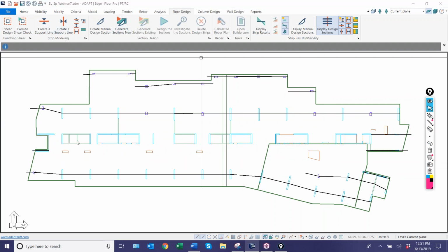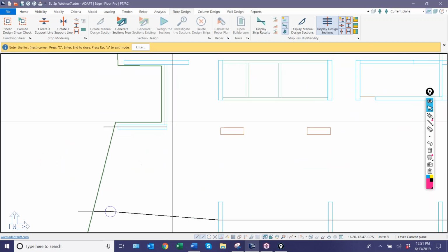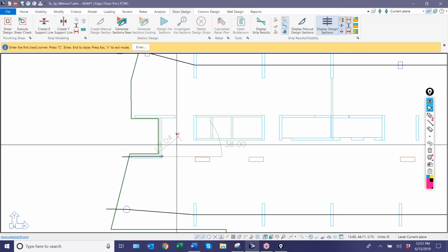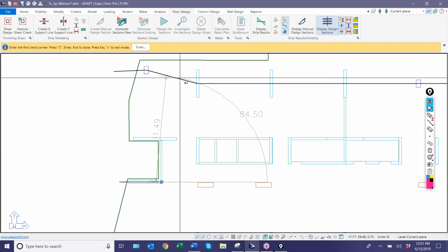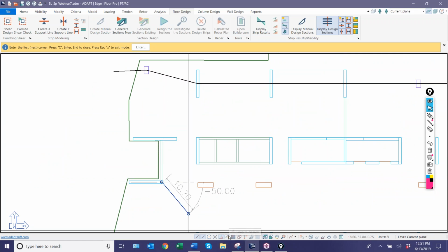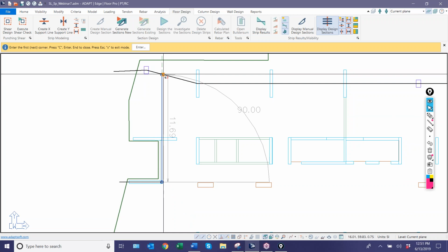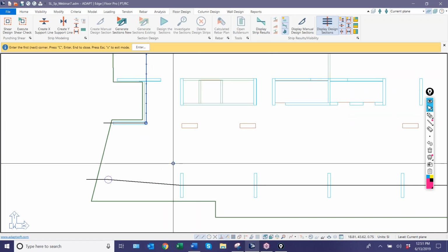So I'll use my X direction splitters. I'll start at this point and I'll just move this up. Now I may not want it to snap at the midpoint or perpendicular, so I'll use snap to nearest so I can try to align it vertically like so.